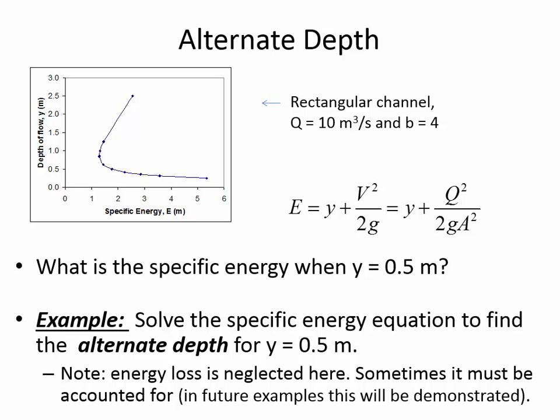What equation do you use to calculate the normal depth? What's that? No, there's one equation that you can use for any different channel geometry. There's a name. It's a person's name. Manning's. Yeah. Okay, so normal depth, use Manning's equation. Okay, it's easy. But how often are conditions normal?